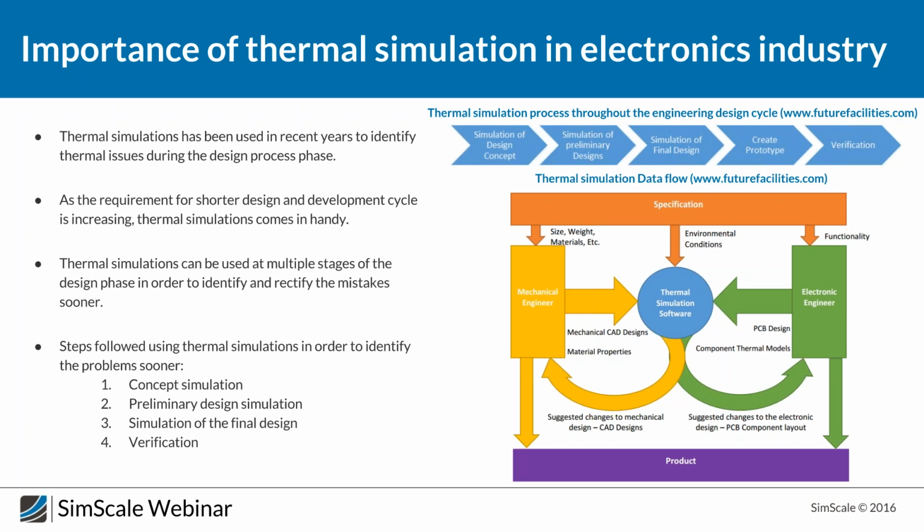So how the components are distributed and mounted also makes a lot of difference. And the heat sink which you are using, for example, to take the heat out of those components is also of real interest. So what type of heat sink you should use and how the components should be placed, so you can avoid overheating of your components and take out as much heat as possible.